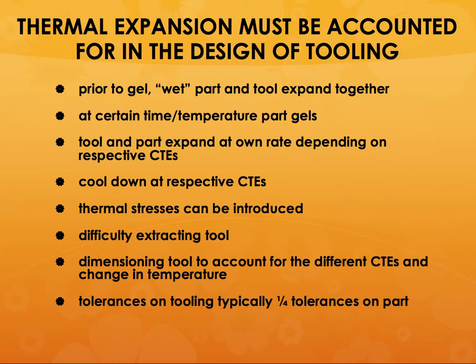The tooling has a mind of its own. It will expand and contract at its own rate and not worry about the part. So, as I said, there will be thermal stresses that will be introduced. And so your part can contract and stick to the tooling, which means it will be extremely difficult to extract the tool after the part is made.